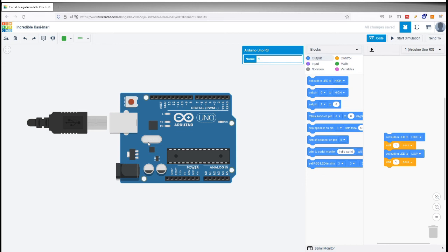I need to make the LED on, then I should give some delay. If you are writing a program in C or whichever language, how will you create a delay? You will be using a for loop or whatever loop it is, and you will be using a variable. You will start counting the variable from 0 to a maximum value in the program. Simply you will start counting from 0, 1, 2, 3, etc. up to a value. So that time taken for counting will be taken as a delay. This is how you are creating a delay, right?